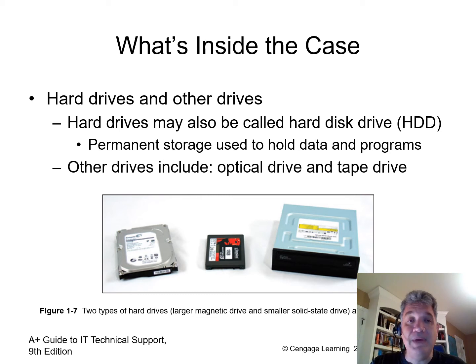Even if it's an older model and you can upgrade to the latest DIMM module, something very fast, for example, much larger than you have currently, it may be larger than what your PC can access. So even though it has the right form factor for the DIMM socket, it may not actually be accessible by the hardware. So again, please consult your PC manual before you buy any new hardware. It may not be compatible with your particular configuration.